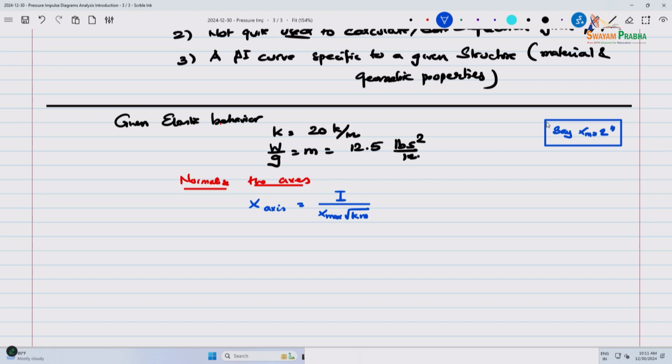And the area exposed, let's say it's a cantilever wall and the area exposed is 1000. This is just illustrative, not an exact example. In this case, it's a blast load, so you have impulsive response, P naught and TD. It's a triangular response.